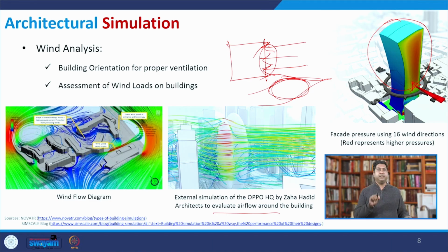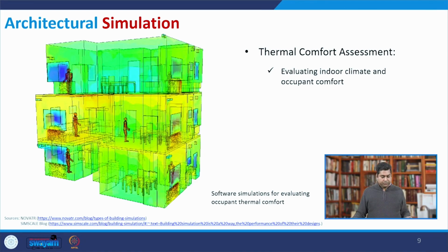Now accordingly you can change the parameters, and what kind of structural system you are going to adopt, whether you go for bracing, whether you go for some kind of outrigger structure, or it can be interior structure, exterior structure, or a combination, whether you go for a single core or split core. So those kinds of structural systems can be determined based on this analysis.